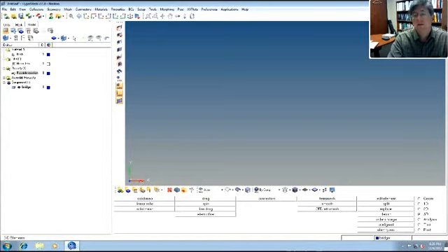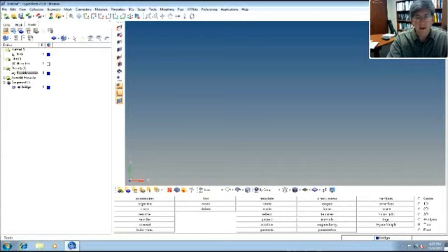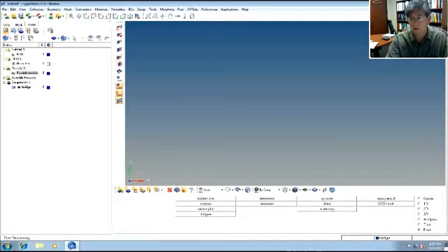Analysis supports things like where we define our boundary conditions, both SPCs, which go through constraints, and our forces, which go through forces, and then also defining the subcases, or the load steps. And then tools allows you to delete things, move things, scale things, reorganize them, count the numbers, calculate mass of your model, and finally you can solve and post-process as well.